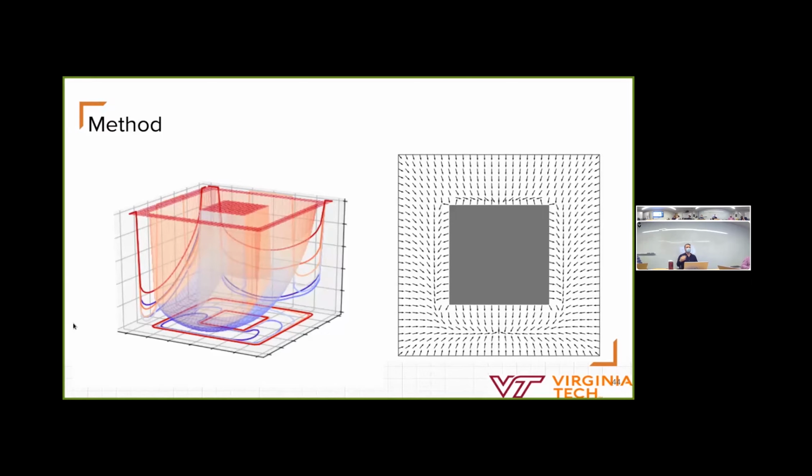A configuration space, another technique borrowed from robotics, is an n-dimensional space where each dimension represents a particular degree of freedom, traditionally of a robot. So for example, an iRobot Roomba would have a 3-dimensional configuration space. It can go X and Y, and it can rotate in theta. And any particular point in that configuration space will represent one unique configuration of that robot, so one unique position and rotation combination.